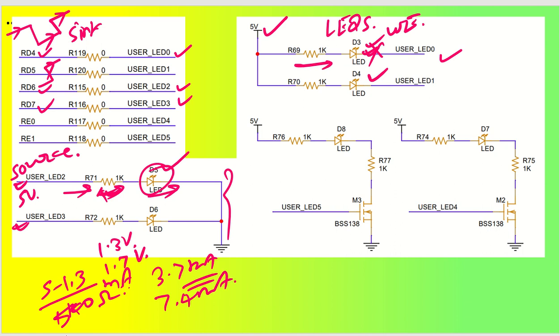So you have to make sure the resistance values must not be so low that the current drawn is more than 20 milliamps, because the microcontroller cannot give you more than 20 milliampere current. So I'll suggest you utilize 1 kilo ohm, or around this value, like let's say 680 ohm or something like that. But if you are working with a 3.3 volt application, then you can go ahead with little lower values, let's say 330 ohm or 470 ohm or something like that.